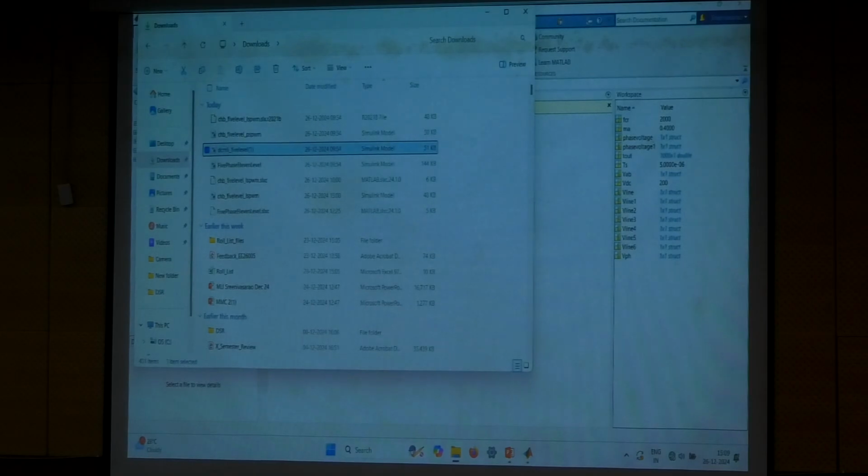So we have capacitors, and we need to balance the capacitors. Sometimes the capacitor balance will be difficult, especially when it is drawing real power, like a motor, or in the case of reactive power also. The load may be balanced or there may be some unbalance, and the sources will be distorted. All will impact the capacitor voltages. Any deviation in the kp, ki parameters will first impact the capacitors. If the capacitors are deviated, automatically all the voltages will be deviated and it will cascade.